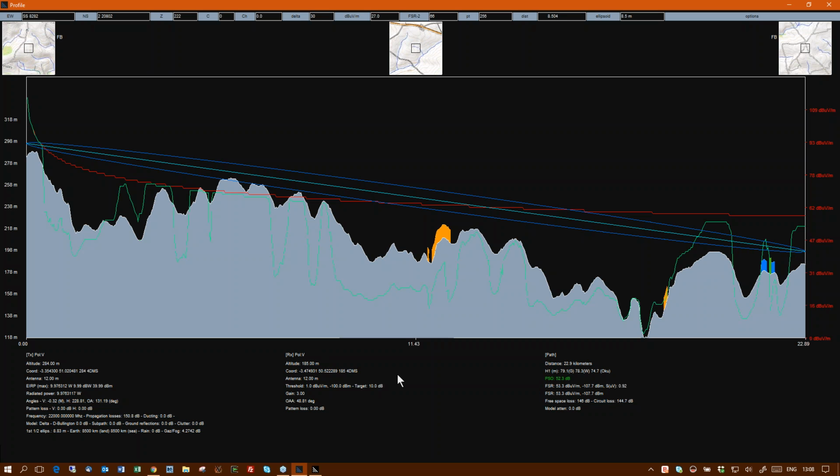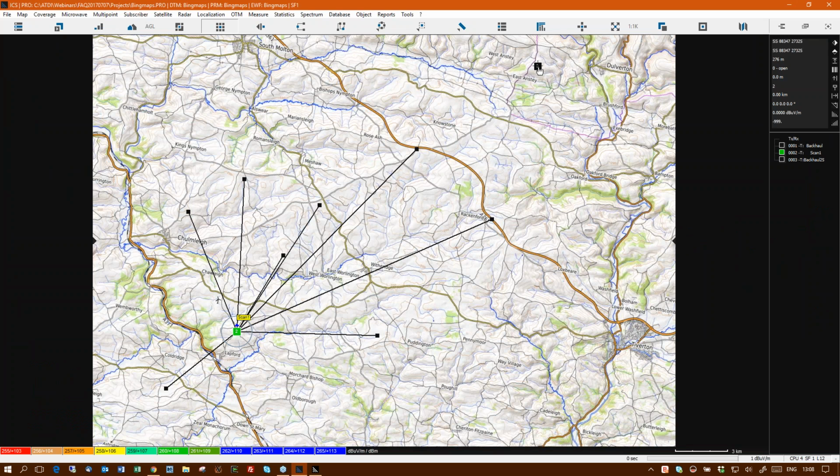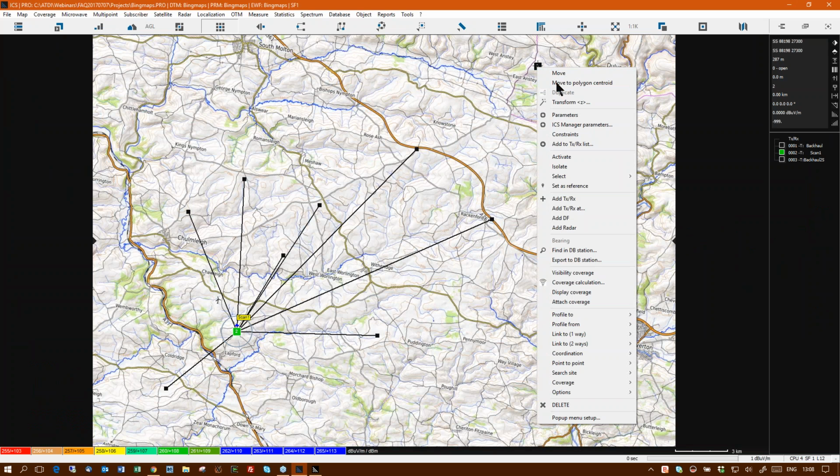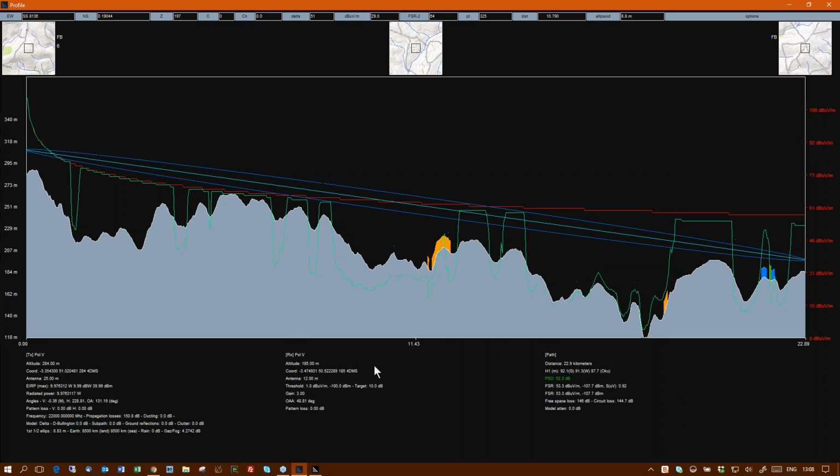And I haven't really put any great effort into defining the microwave link. It's just a path. After this, you go into detailed planning. But there's a bit of intrusion, so we'll have to lift this end up a bit somehow, which I've already done. But ordinarily, you'd be able to do it from within that path profile. So now I've lifted it up to 25 meters, and now we've got a clear line of sight.